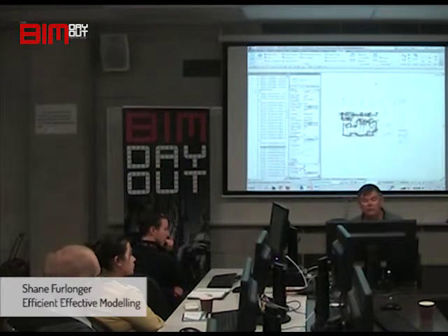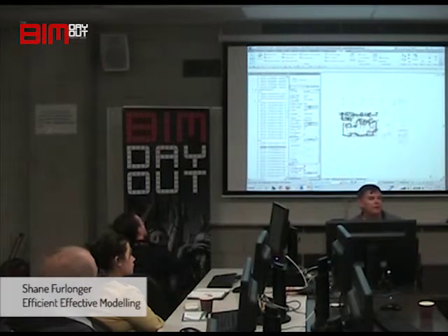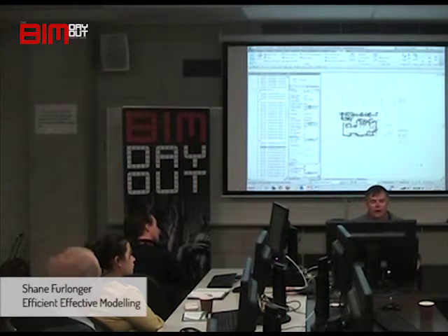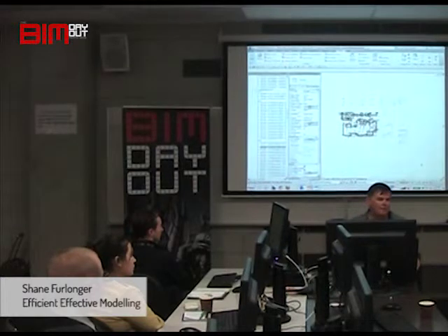If you get the warning message straight away, like I said, when that warning message pops up, the first thing I do is I click on it and expand to see what's going to happen. So, what is this message? Okay, I've got duplicate type mark. Now, that's not a good thing. You don't want to have duplicate type marks. Duplicate marks are okay because they're just an individual thing.